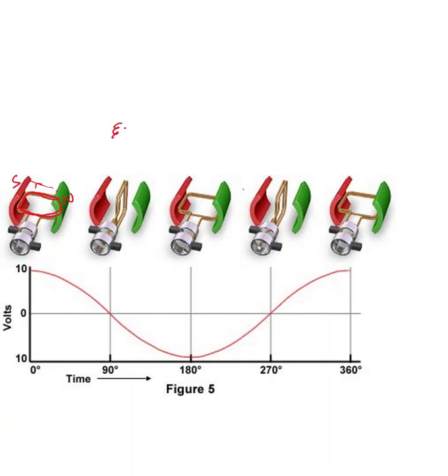According to Faraday's law, there is always an induced EMF as long as there is a rate of change of magnetic flux. Here phi is called magnetic flux, and phi equals B times A times cos theta, where theta is the angle between B and the normal to the area. B is the magnetic field in Tesla, and A is the area in meter squared. If you take a paper and put a pen perpendicular to it, the angle between the paper and the pen is 90 degrees. It is sticking out of the screen if I take the screen as my rectangle.